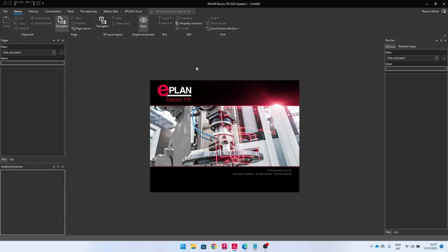I'll now do the same exercise in EPLAN Electric P8. I'm running the compact version that is quite a lot cheaper than AutoCAD Electrical. But let's see what we can do. When working in EPLAN, opposite to AutoCAD, where you are working in separate drawing files and you have this project database on the side that will be kept up to date by running the special AutoCAD Electrical commands, in EPLAN you pretty much work in the database all of the time.